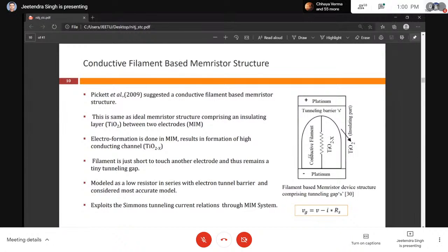So these oxygen vacancies are conductive in nature, so they also work as a metal. We call it a conductive filament; it has the same nature as the metal, because it is very highly conducting. So in our basic structure, we apply a high voltage for a certain duration, and we develop a conductive layer. This is a one-time process. There is no need to develop the conductive filament again and again. When we have the fabricated device, we just have to program it one time.